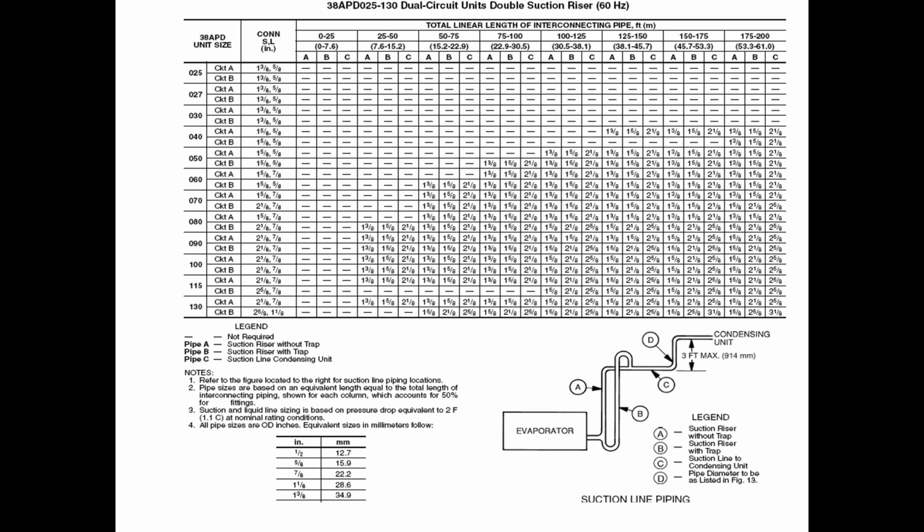And hey, are we at 50% equivalent length in fittings? So take your fittings and look at your long line, your linear length, 100 feet. Well, if I add up all these fittings, do they total up more than 50 feet? If so, then you can run into problems there. Okay, so this linear length chart has 50% built into it for fittings. Just make sure you don't go over that 50% number with additional fittings like that.